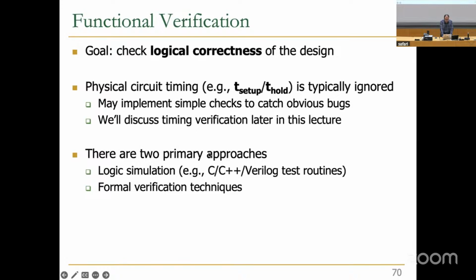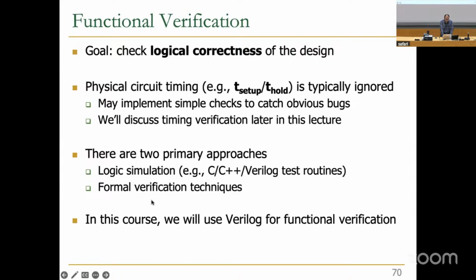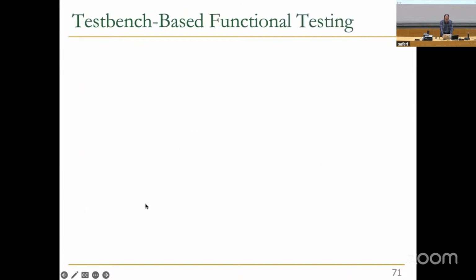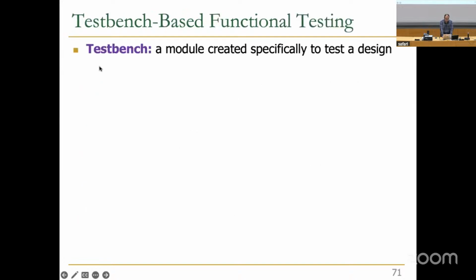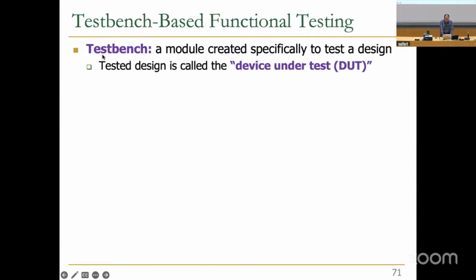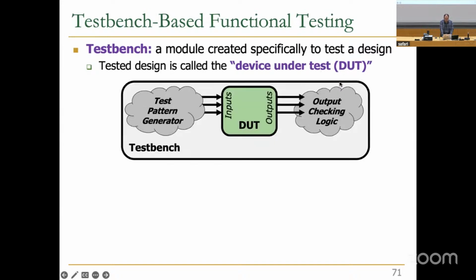There are two primary approaches. One is logic simulation using C, C++, Verilog test routines, or using formal verification techniques like SAT solver, for example. But in our course, we actually use logic simulation. So let me introduce you to Test Bench. A test bench is a module created specifically to test a design. Our design that we want to test, we call it the device under test, which is DUT.